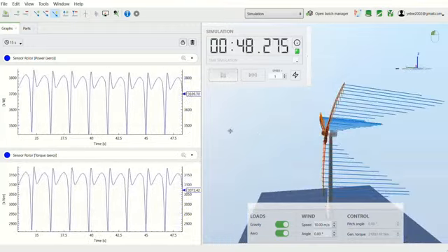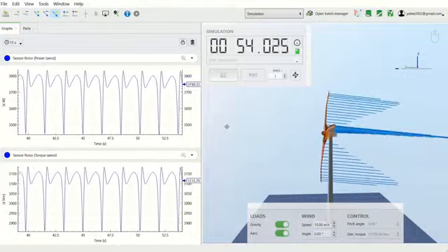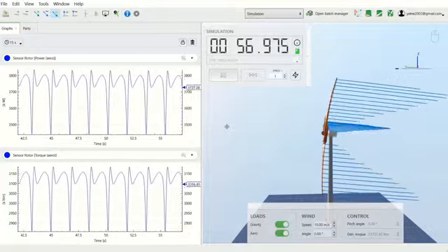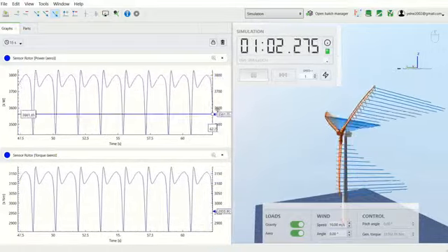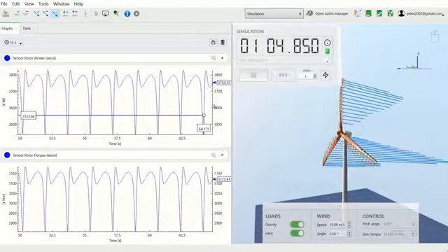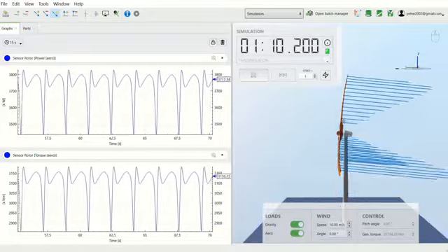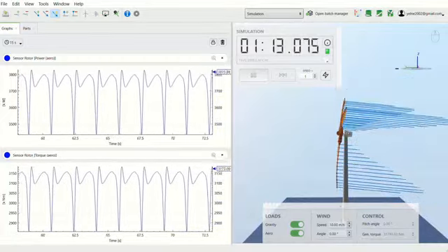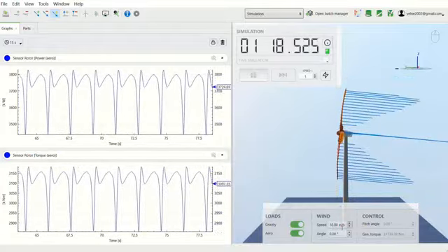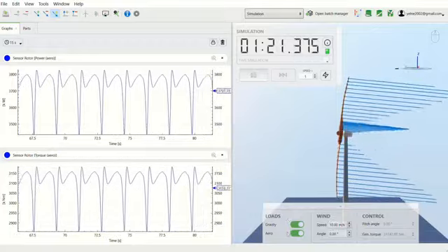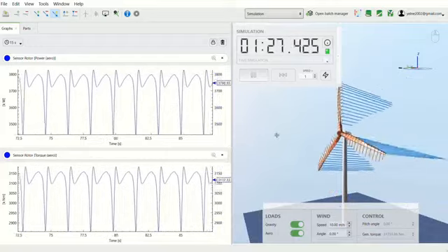As the wind cuts the tower, the redirection of wind takes place and the 3P effect in one single rotation of the wind turbine is observed. These effects cause pulsation losses in the electrical generation in power quality analysis. The pitch angle, or the blade angle, can be changed by pitch controllers. As you can see, the speed set is 10 meters per second. Gravity and aerodynamic loads are considered. These effects occur in dynamic.